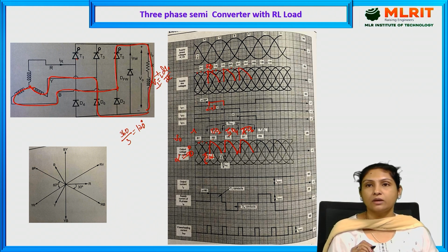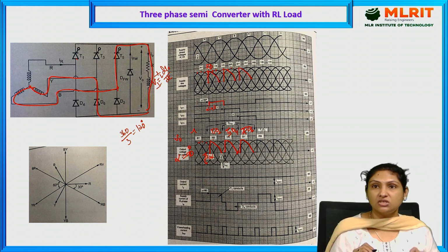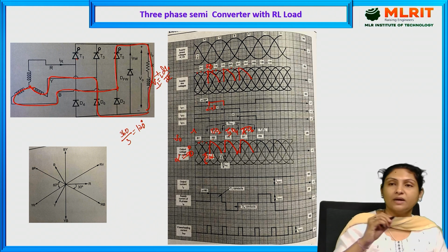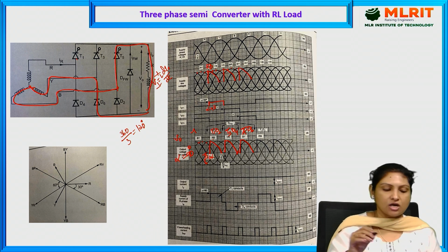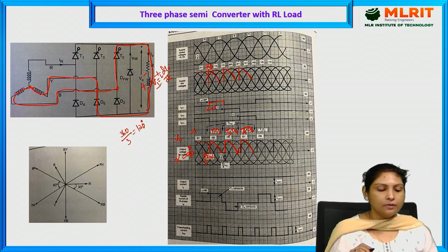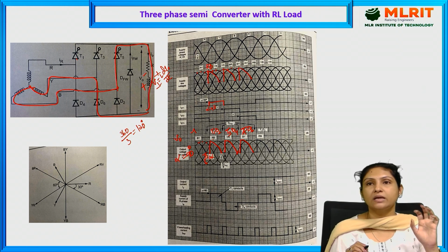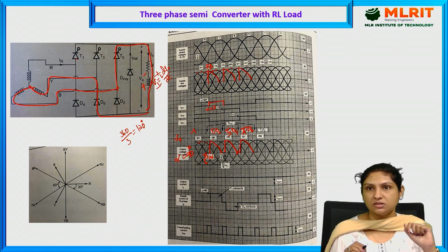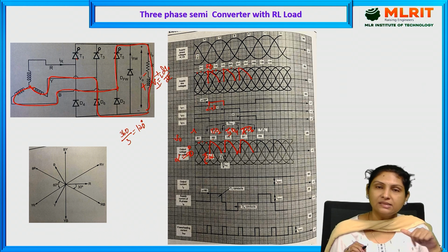At the same time, the inductor reverses its polarity by the time it is completely charged, negative, positive, because the inductor does not allow any sudden change in current and tries to maintain the current through the load in the same direction.